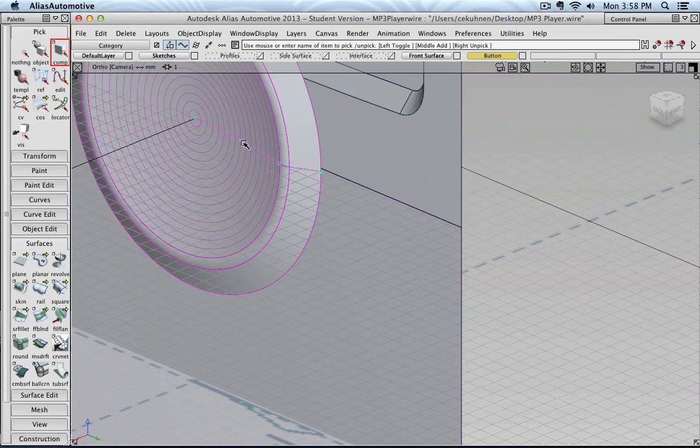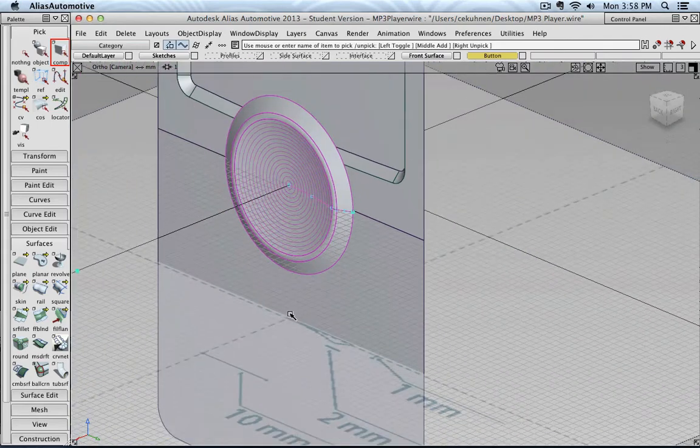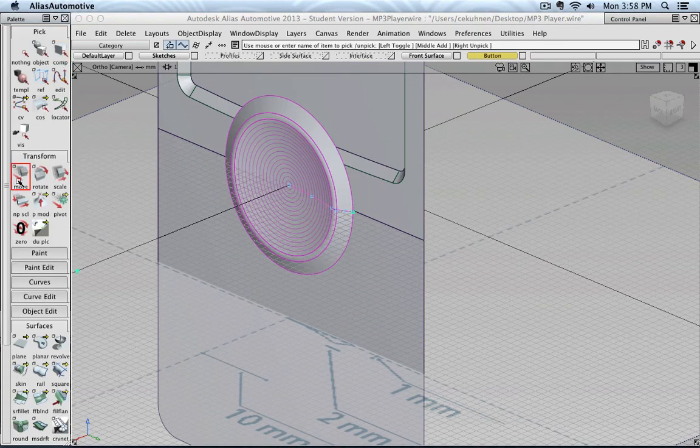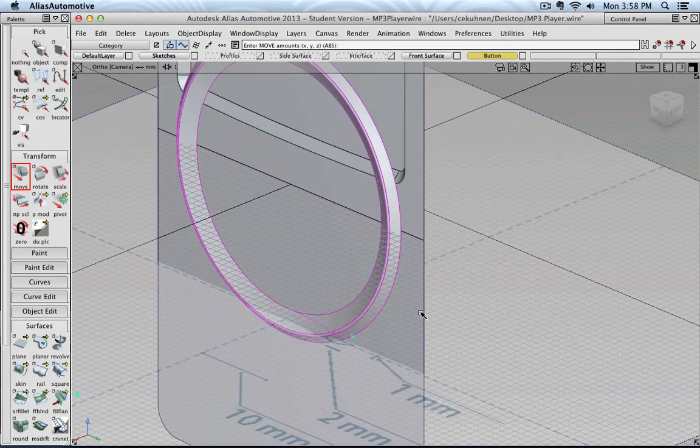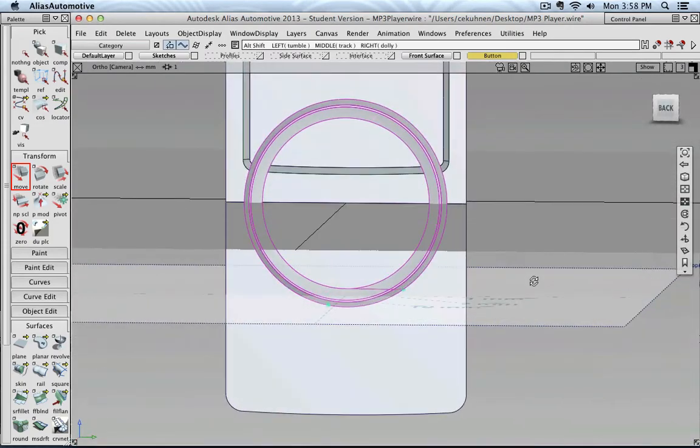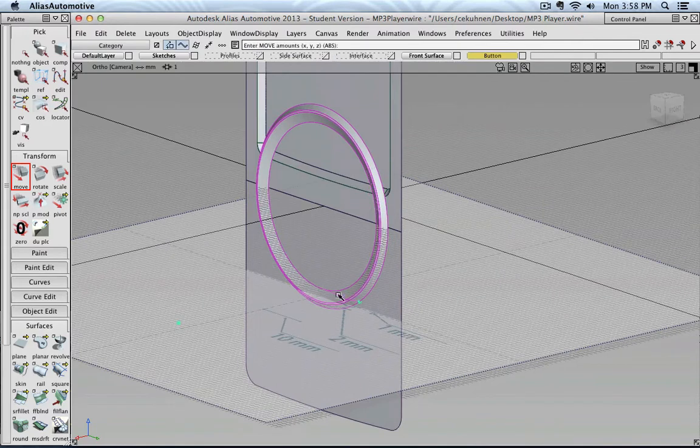And when I move the line and the arc, the fillet, which is a feature, will follow this anyway. If I now go to transform and move, and in perspective view press my right mouse button and move it down, I can maybe try to hit some at the center here, release my mouse button, and wow, the Revolve tool stayed where it was, and I moved my curves only down. So what's going on here?